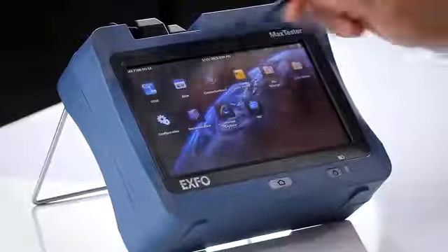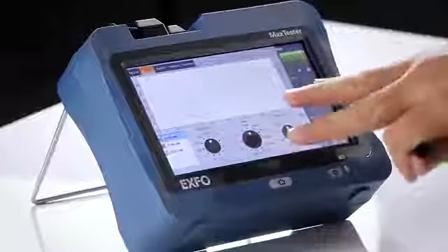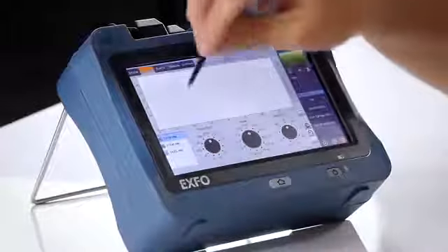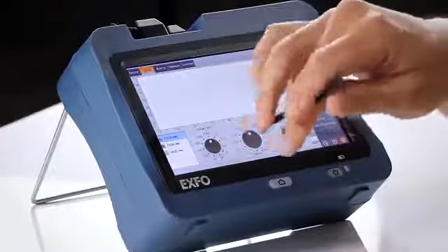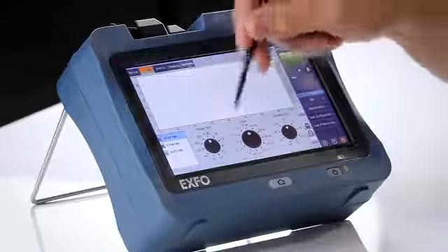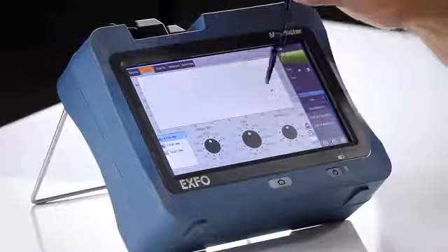All right, I'm going to go ahead and launch the OTDR module. So we'll select on the icon, and it just takes a few seconds. And so now here we are in the main OTDR screen, on the OTDR tab. We can start stepping through the GUI and setting up the configuration. We have different tabs on the top. You have the source that allows you to turn the source on and off. So this unit can be used as a continuous source, or you can modulate the signal. So over there on the bottom left, we have 1310, 1550, and 1625 as the options that are on this particular module. Just to the right of that, we have the three knobs where you can set your range, pulse width, and duration. And so we'll get into a little bit of that when we set up the unit itself.